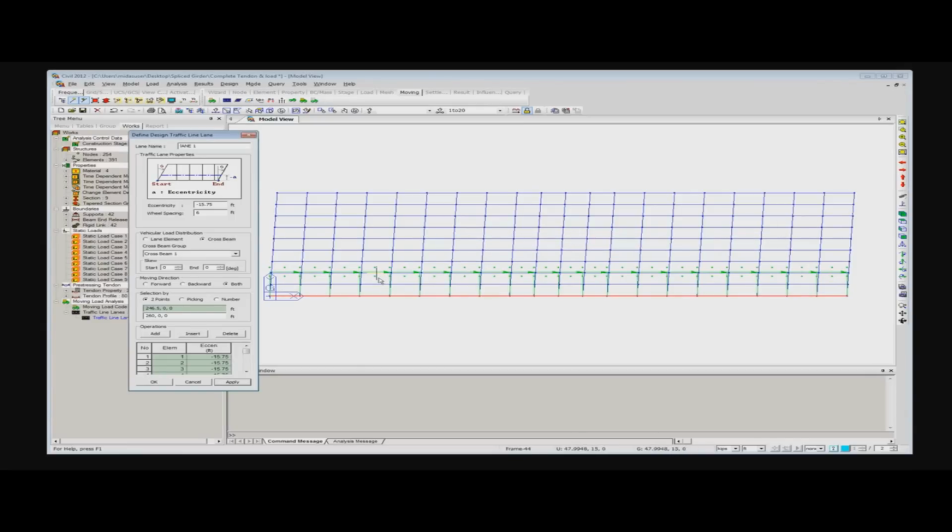So for now we can do something. We could ignore that skewness, or we can define that. So for that reason, I can simply here in the skews apply 2.5, which I showed you in the beginning, and then 2 points from here to here, and apply. You can see that it's exactly following that skewness.